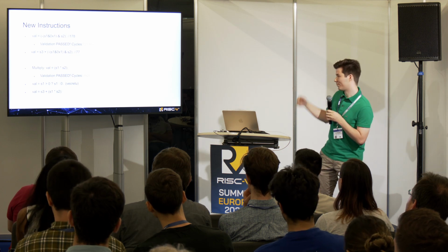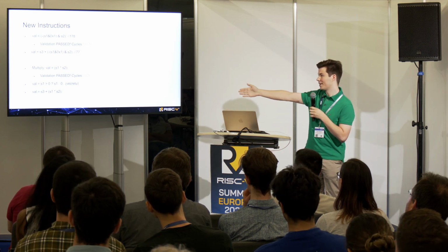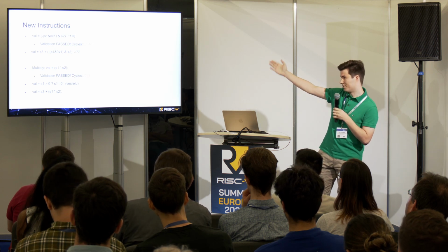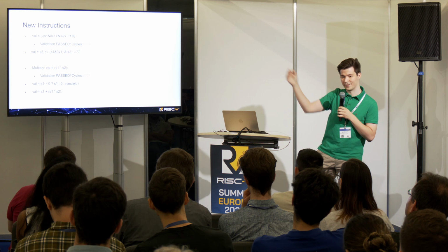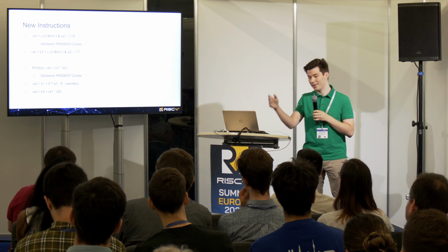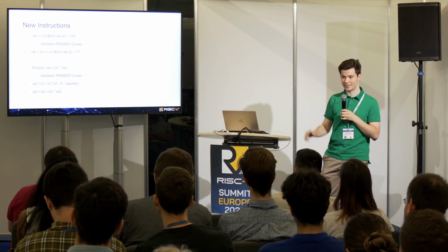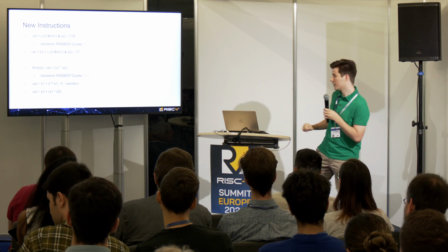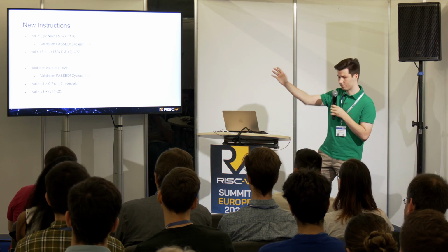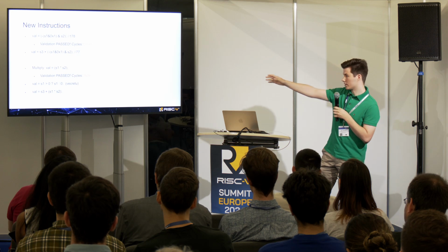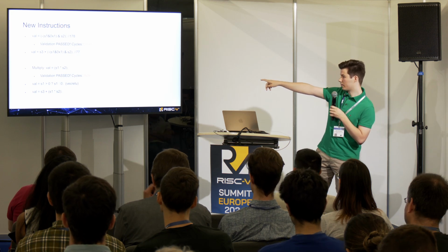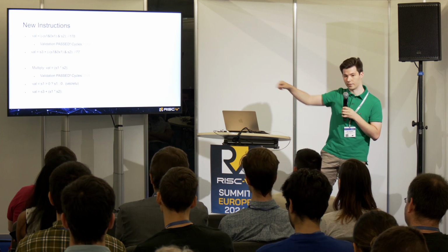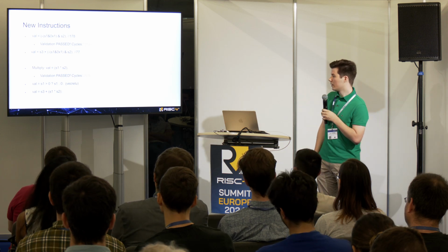But if we just look at the source code and implement a single multiply instruction, we already go down to around 3,500. So it's a speedup, but for this small example, it's in many cases easy to just look at the source code and implement some of the main functions, which I also did, like most of you already presented. Just implement the multiply, accumulate, and the redo function, which is used very frequently.